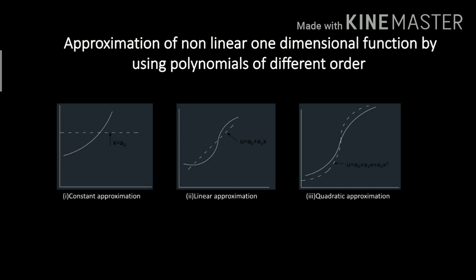Here, in the first figure, since the polynomial selected for the formulation of the shape function is poor, there is only one common point between the actual curve and the curve generated based on the shape function. In the second figure, two points are common but not matching with the actual profile, so it's of no good either.